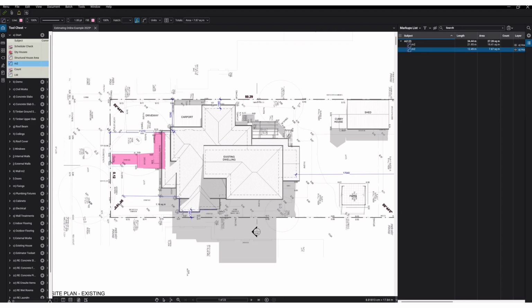As you can see here with my style of estimating, I am not being perfect with how I'm measuring. I'm measuring close enough is good enough. As we are trying to set a budget for the construction cost of the project, we want to be as fast as possible. It doesn't mean we have to be as precise as possible. To be honest, we don't really even need to take this step of doing a proper accurate measure. We could say 200 square meters of paving, go straight into our program and add 200 square meters of paving.